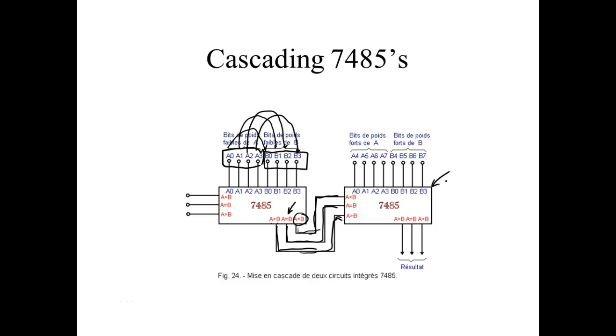And it had a sensor on there that, while the XYZ moved, would send pulses out. Then the pulses would go through a counter, and we would compare what the operator set on those thumb wheel switches to the counter, and when they were equal, it would know it was at the right spot. But all the comparators were done with nothing but transistors. We came in, and one of the sets of transistors was bad. So what do you think I did? I replaced the whole section with a 7485. As far as I know, the milling machine is still working.